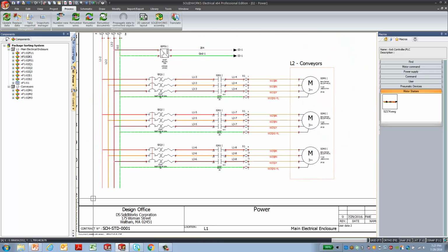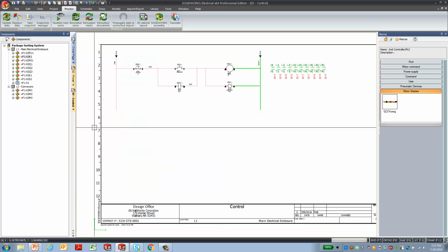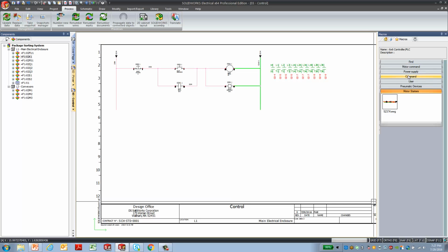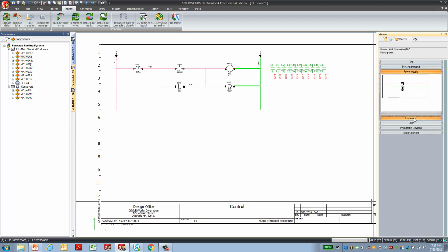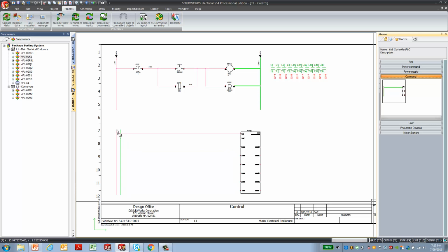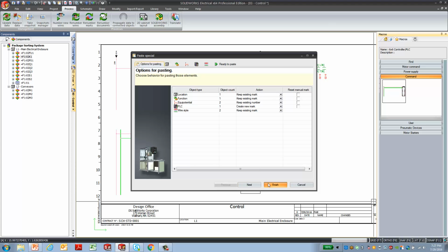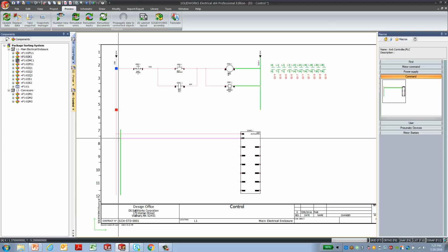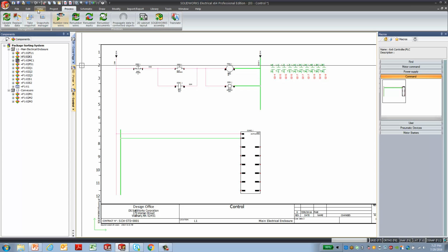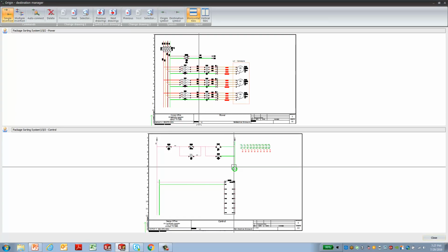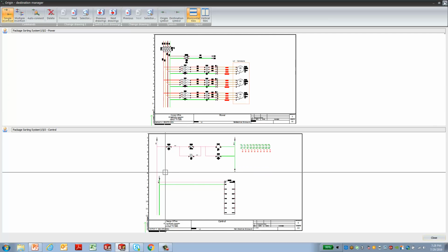So now that all 3 conveyors are powered, we'd like to add some sensors and some pneumatic devices to detect and divert the packages as needed. So let's start by adding a symbol for a small 6x6 PLC device. Since all the information comes through in the macro, as well as the connecting wires that I need for this, we'll finish. And we'll just connect the power, and I'll connect the ground with, why not, another one of those origin destination arrows. Connect ground to ground. Perfect.